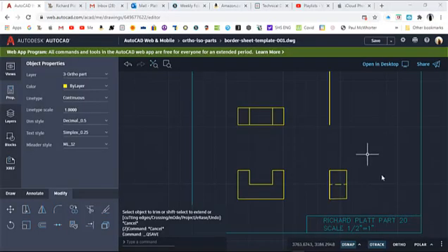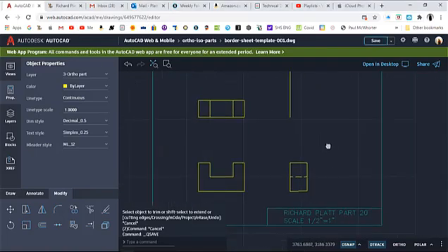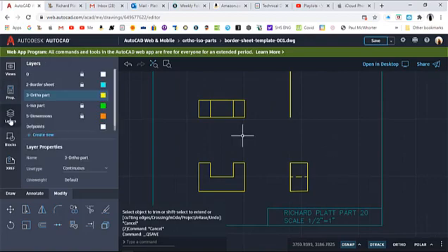Okay. Seeing where we are right now, we've got our top, our front, and our right view drawn. It's a very simple part, but it's a lot simpler when you know the actual dimension you got wrong, so I'll have to fix that for my paper drawing. But now we're going to draw the isometric. So let's go to layers. Let's go ahead and select the isometric layer, double click it, come up here and lock the ortho part layer, and let's unlock this guy here so we can start doing this.